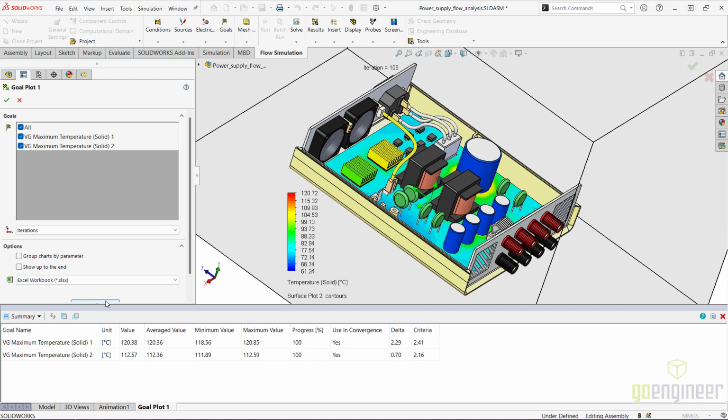We can see that our IC temperatures here are much greater now, and they reflect the result values of a more accurate setup due to the Electronics Cooling Module. The temperatures for the ICs now in the maximum column are about 112 and 121 degrees Celsius. Again, super toasty. We stand no chance with this type of forced convection cooling, right?